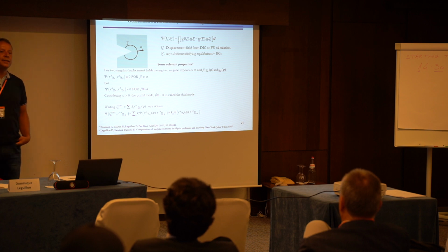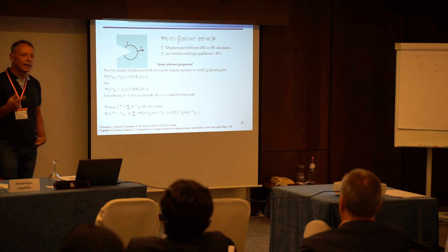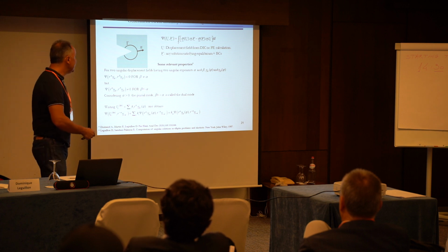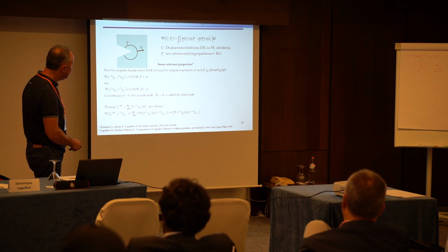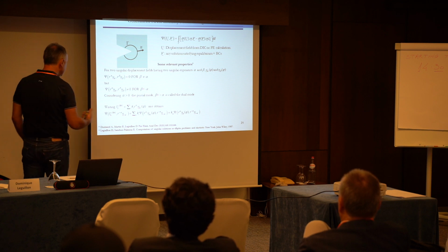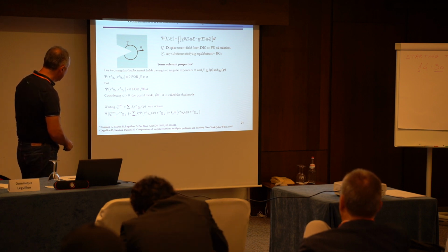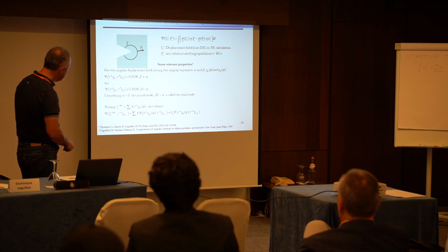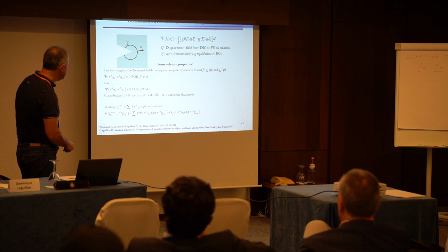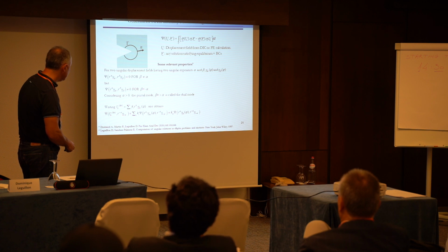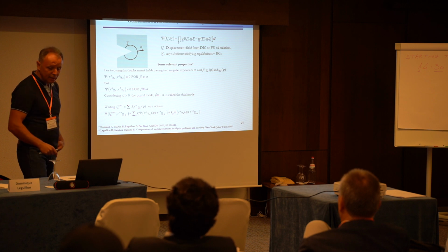And the dual mode is, in the spirit of Hild, Roux, and co-workers, the super singular mode, but in fact it is very similar. So what are we going to express? We have the measured displacement field, and by assuming this auxiliary field, somehow we are able to derive the generalized stress intensity factor that is here.